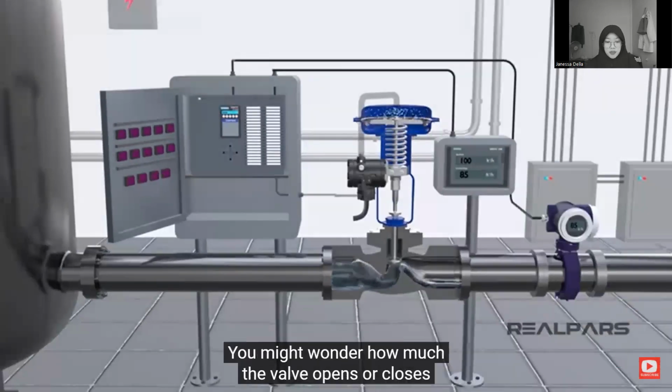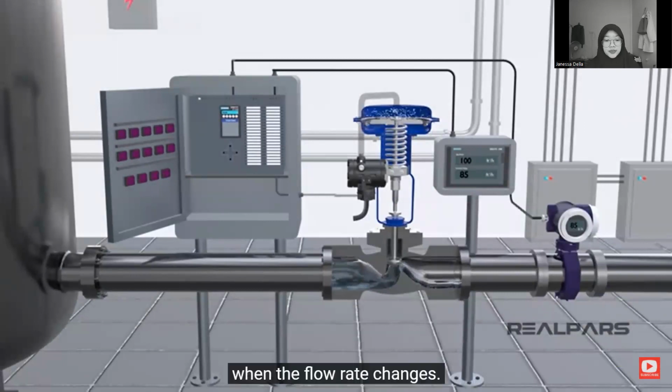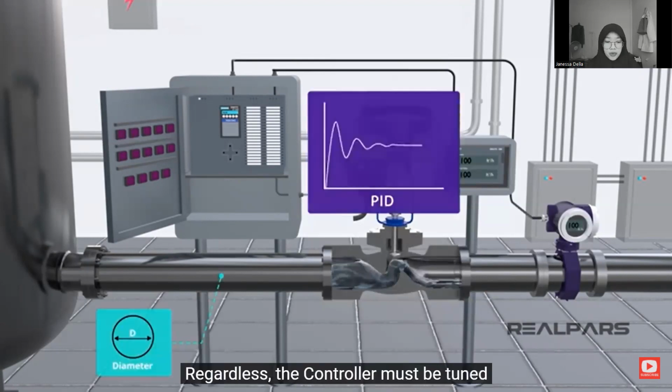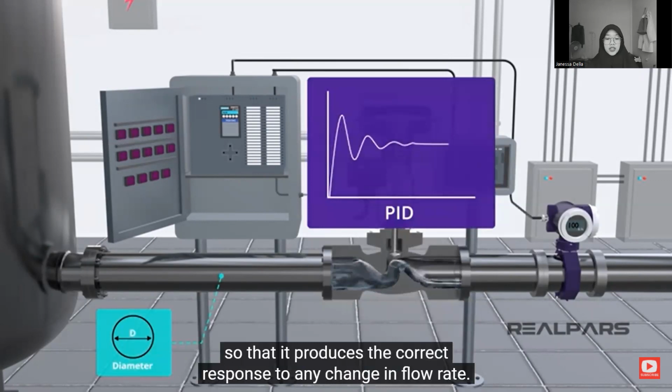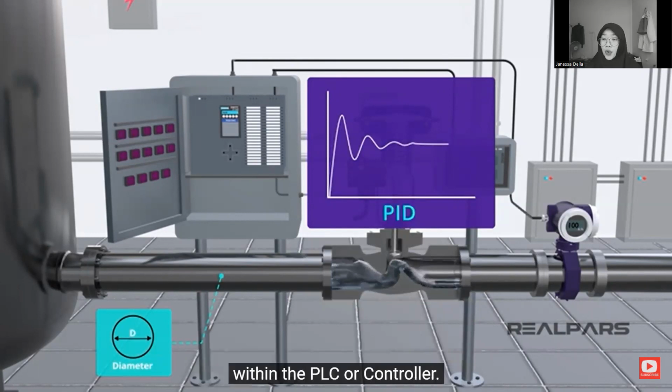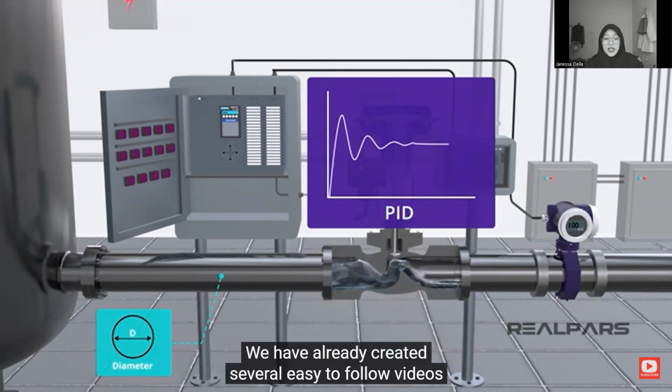You might wonder how much the valve opens or closes when the flow rate changes. Well, it depends on a number of things, such as the percentage of flow rate change and the diameter of the pipe. The controller must be tuned so that it produces the correct response to any change in the flow rate. This is most commonly achieved by using PID in the PLC or controller. We have already several